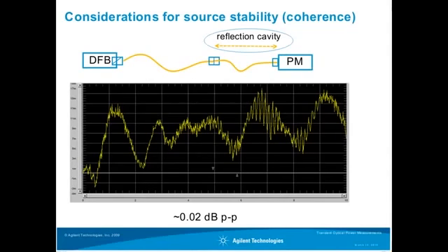All we've got here is an open fiber connection at the power meter. That's pretty typical. Usually our power meters don't make physical contact to the fiber, but instead the fiber just ends here. And if it has a straight polish connector, that's about 3.5% reflection, 14.8 dB, whatever. That amount of light is going to come back this way. The DFB source in this case is isolated. That shouldn't really give us any trouble. We have an angled connector here, but we put a straight connection, and actually a fairly good one, in at this point, and that can reflect maybe a 40 dB return loss.